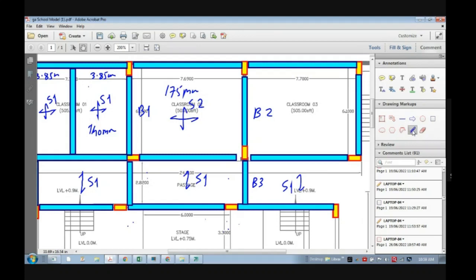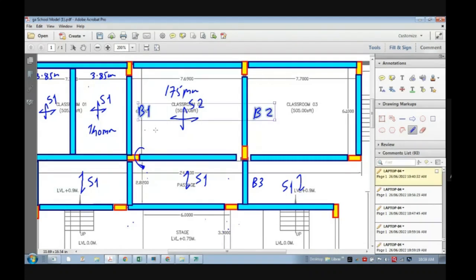एक second में. So this is your bending moment on the weaker axis developed due to B1. And this is also a bending moment here, but you will see that this bending moment is on the major axis and this is on the minor axis. And definitely whenever moments are more on the minor axis, the steel requirement of the column is more.